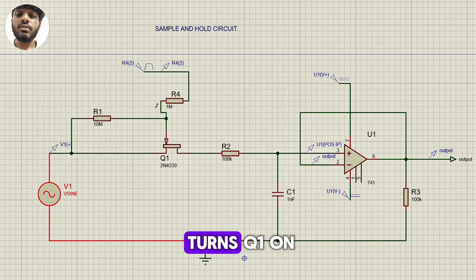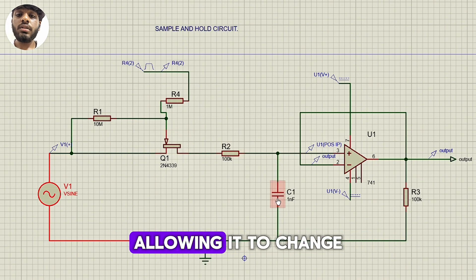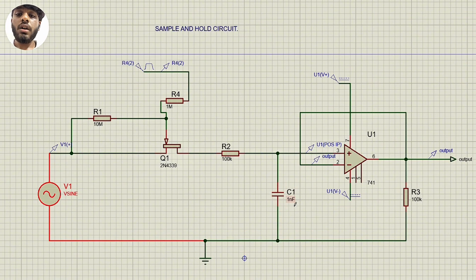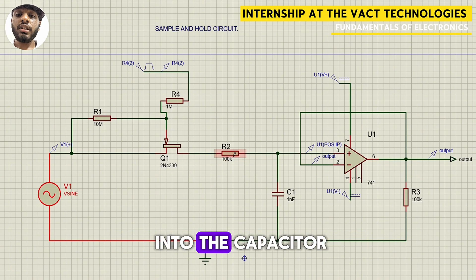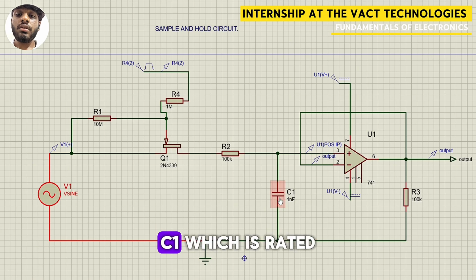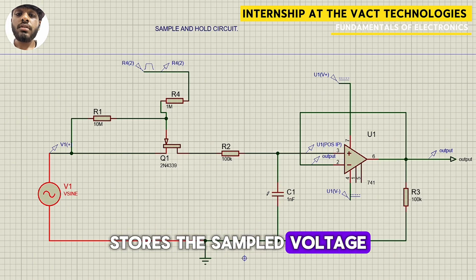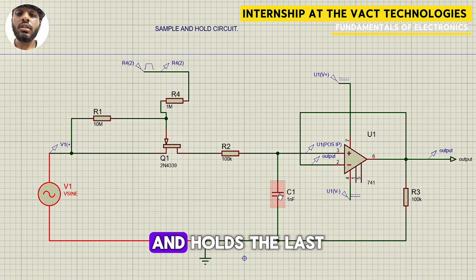Sampling operation. When the clock pulse turns Q1 on, the input signal is connected to the capacitor, allowing it to charge to the instantaneous input voltage. R2, which is rated as 100 kilohms, limits the charging current into the capacitor and improves circuit stability. C1, which is rated as 1 nanofarad, stores the sampled voltage. When Q1 turns off, the capacitor is isolated from the input and holds the last sampled value.